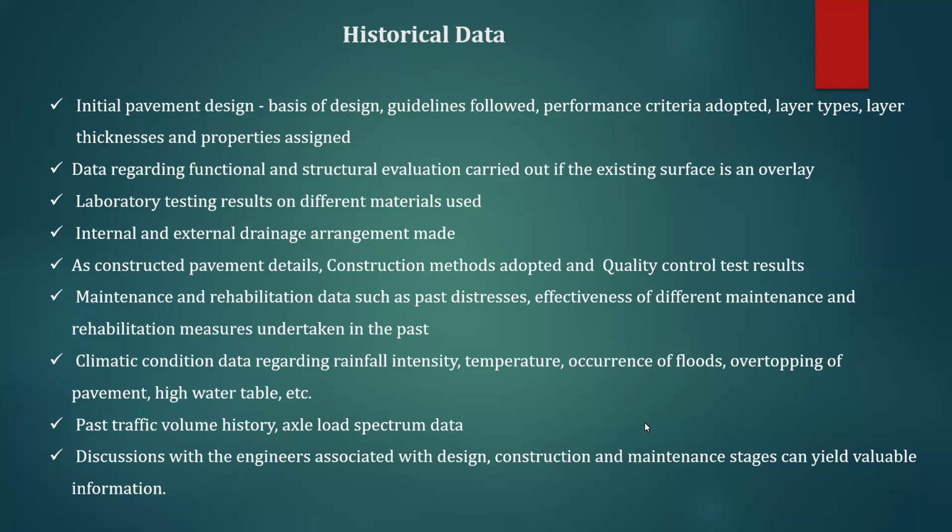You know that we never expect that always a standard axle of 80 kilonewton will come onto the pavement surface. IRC has considered 80 kilonewton, a standard axle with a set of dual tires on both sides, but a standard load will not always come onto the pavement surface, we expect more heavy weights. So using the fourth power damage law, we will try to calculate that vehicle damage factor.